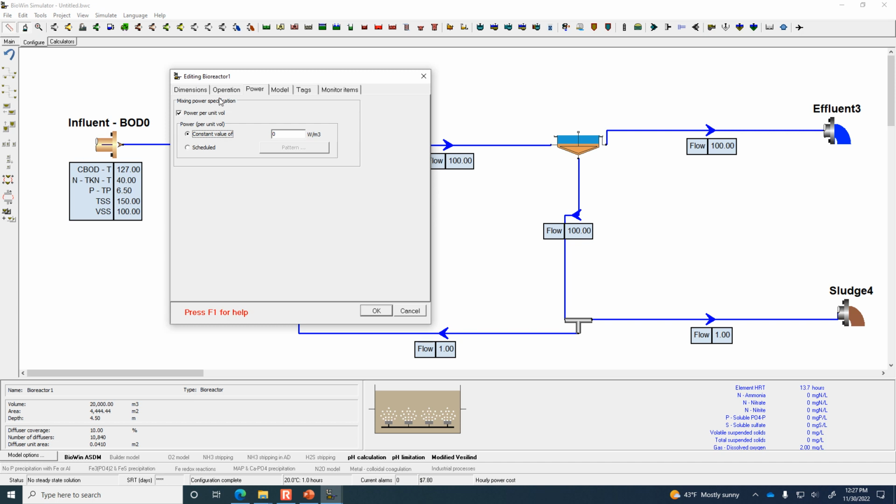And then there's an economic model running in the background where if you tell it the price of electricity, then it can generate a report that tells you what is the cost of operating the wastewater treatment plant. And you can define things like the cost of chemicals, the cost of sludge processing. And so then that would allow you to go in and try and minimize the cost of operation by trying different combinations of chemicals to improve the performance while balancing out the economic consequences as well.